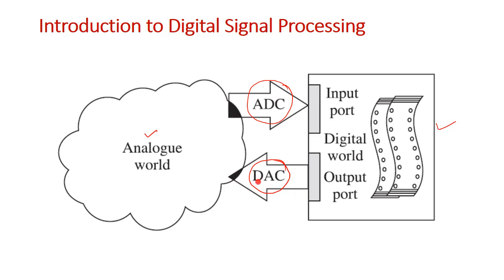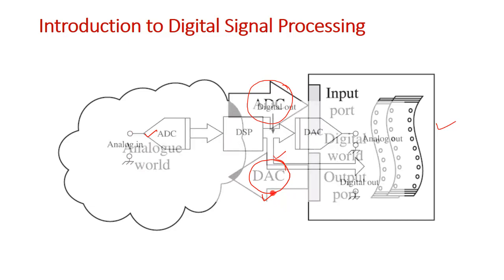In fact, in case of a power system, when we give the trip signal it is in terms of 0 and 1, so it is a digital signal. Therefore it is not essential for protection purposes to convert the digital signal from the numerical relay to an analog signal. Therefore we do not require a DAC in case of power system protection applications.